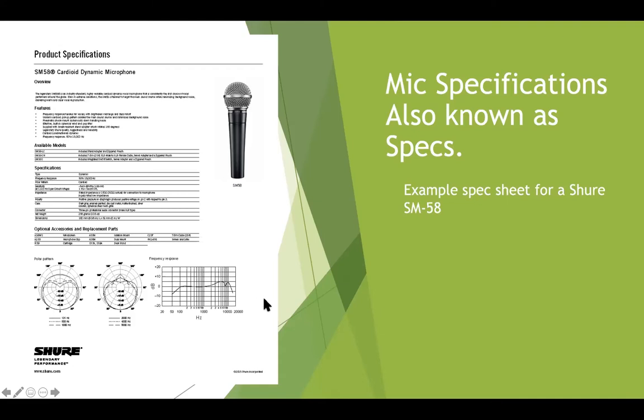The frequency response, so here's a graph that shows you how flat the microphone is. Now this microphone has what's called a peak from 2,000 to 7,000 cycles. And what that means is it's more responsive here. So if this microphone was going to be used for accuracy, it would not be suitable. For accuracy, you want the frequency response to be 0 all the way along, what's called a flat response. You want the microphone to not add any energy or take any energy away. You'll notice, for example, above 10,000 cycles, which is this last section here, the line drops down. So that means the microphone's less sensitive and recording less and less energy as we go higher in frequency.